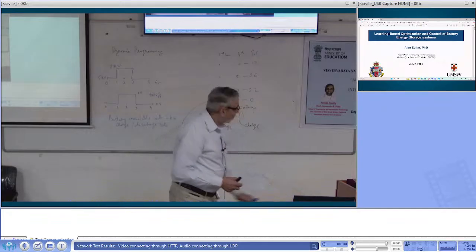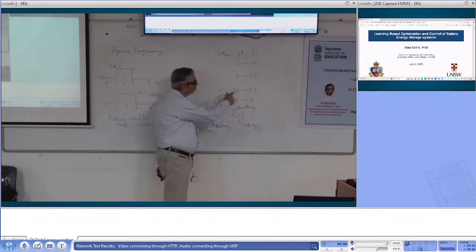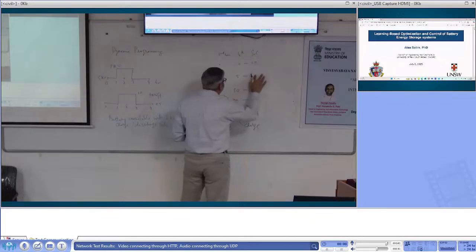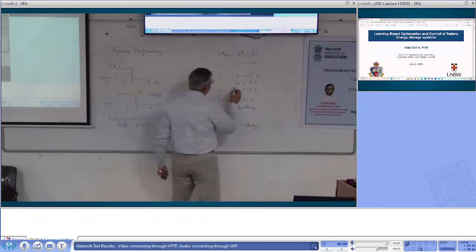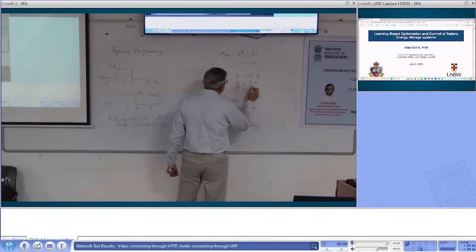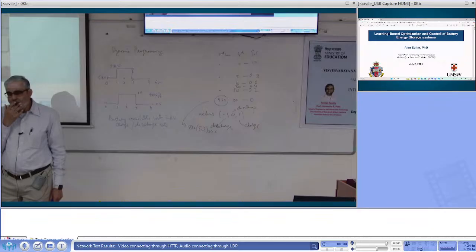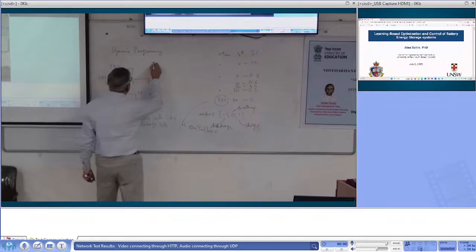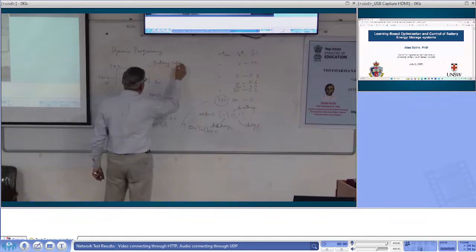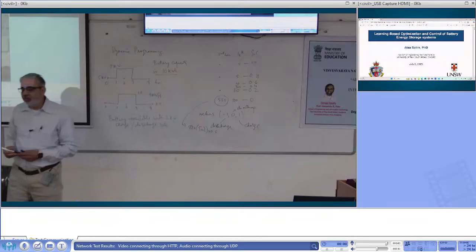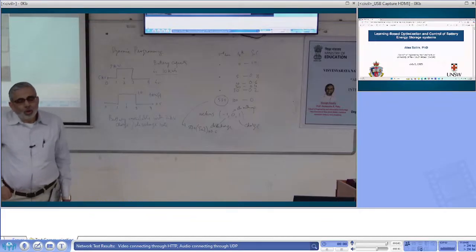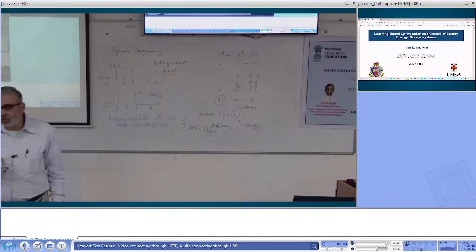So if I charge, I'll end up here, because 0.2 is my charge. Well, no, I made a little mistake. I can't escape that. 0, 5, 10, let's say 0.6. I have to have 0.6 also, 0.4 also, because charging is only 0.2. So, sorry, I jumped a little bit. So, battery capacity. I'm very sorry. The battery capacity is 10 kilowatt hour. So when you charge it for an hour, it gives you a charge or discharge at the rate of 2 kilowatt. It changes the state of charge by 0.2, right?